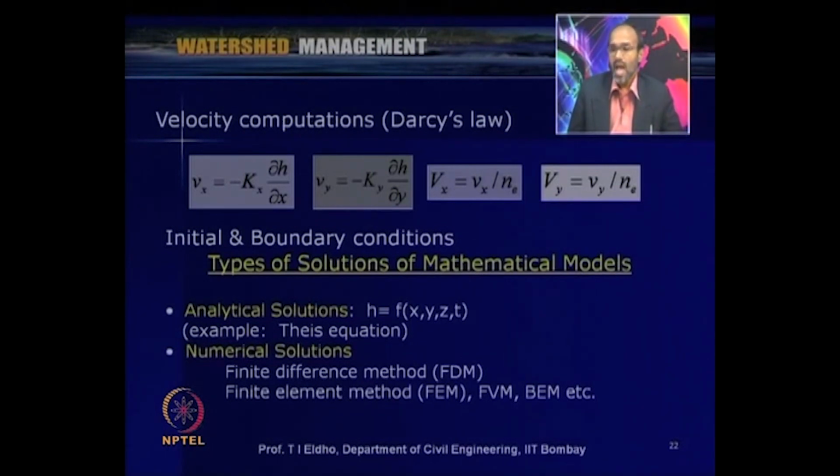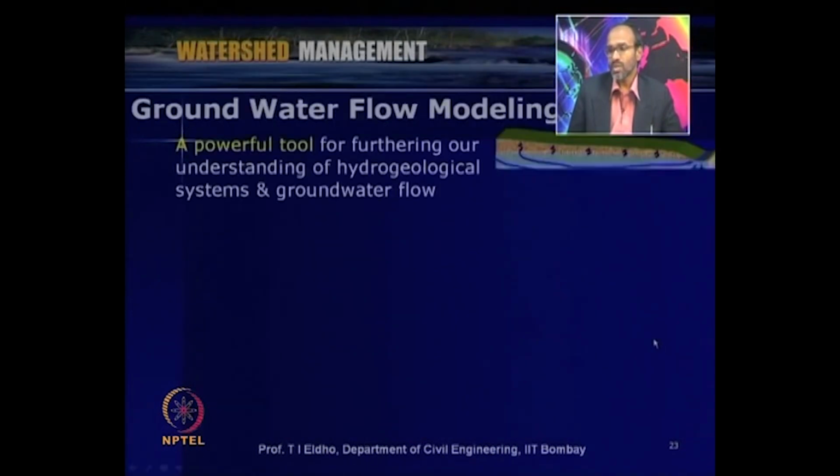As I discussed in the previous lecture, various numerical techniques are used to transform these second order partial differential equations into algebraic form, using techniques like the finite difference method, finite element method, boundary element method, or finite volume method. In the last lecture we discussed methodologies like the finite element method and finite difference method. Nowadays, a method called the analytical element method is also available for the solution of groundwater flow and transport equations.